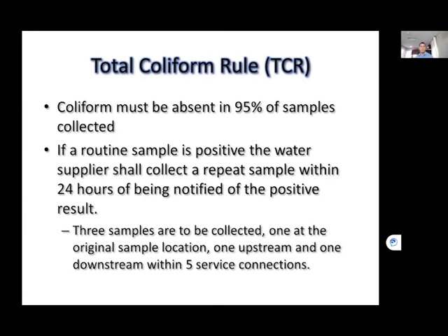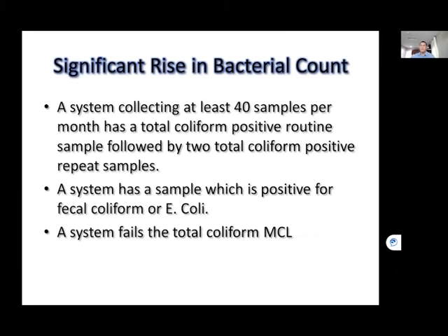So at the treatment plants, we are requiring low turbidity levels and also to maintain disinfection. And then when you get out to the system, we're monitoring for elevated coliform levels to see if there's any type of significant rise in bacterial counts.